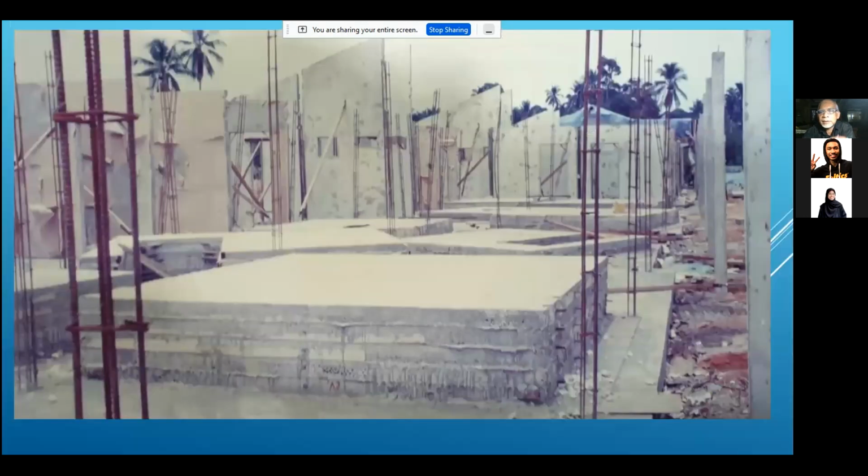This is how we do repetitions of wall. I can just put a few layers of wall having the same size. You can see that there's a plastic layer in between. The plastic cannot be very thick. When it's very thick, it starts to fold, and then you create a lot of lines. Plastic must be very tough and very thin, so that when we put in the concrete, the concrete is pressed over the plastic, so that it doesn't have so much unfolded groove line.